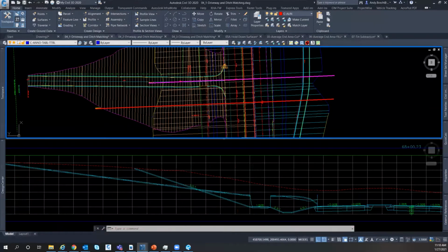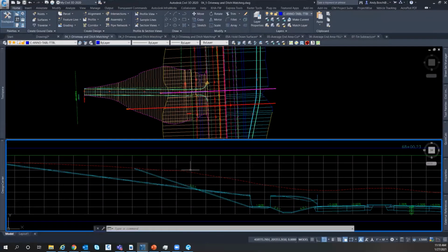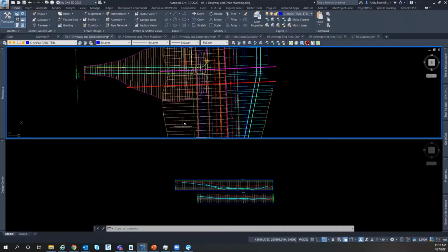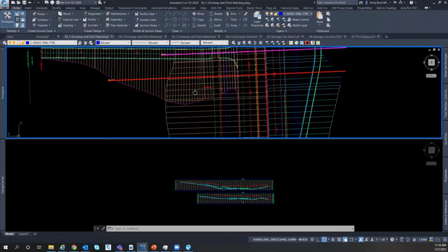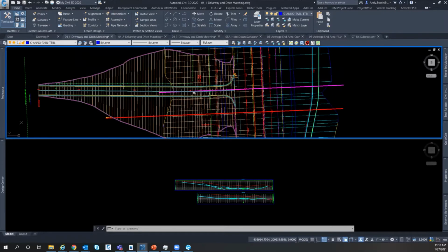So how do we solve this scenario? And the best way that I found, and not that this is easy, is what I like to call an auxiliary corridor. What I have is another corridor running down this side that is doing basically everything that my mainline corridor is doing, but I'm not omitting these areas where I'm going underneath the given driveway. It's building out completely through that.